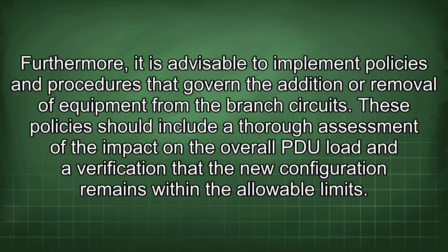Furthermore, it is advisable to implement policies and procedures that govern the addition or removal of equipment from the branch circuits. These policies should include a thorough assessment of the impact on the overall PDU load and a verification that the new configuration remains within the allowable limits.